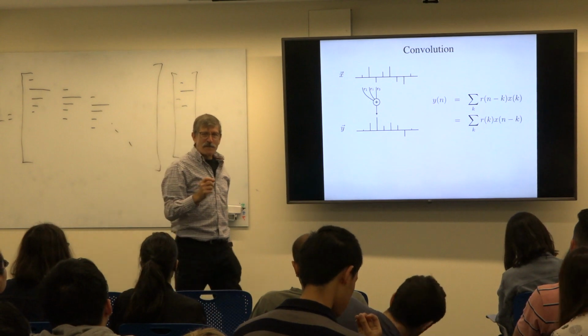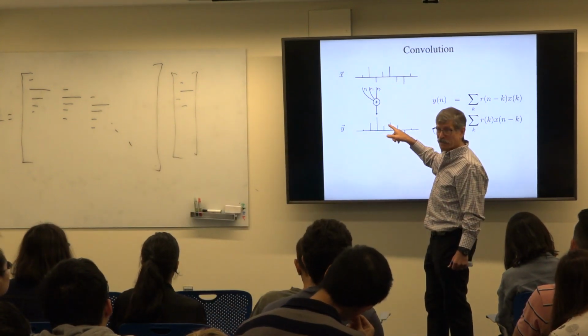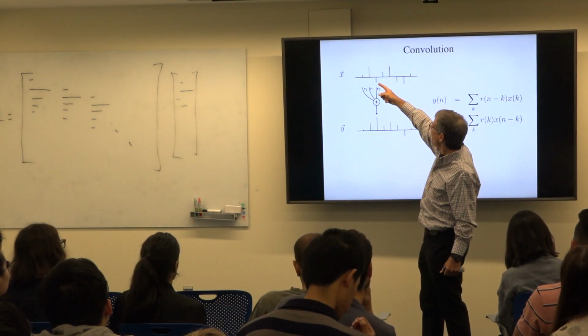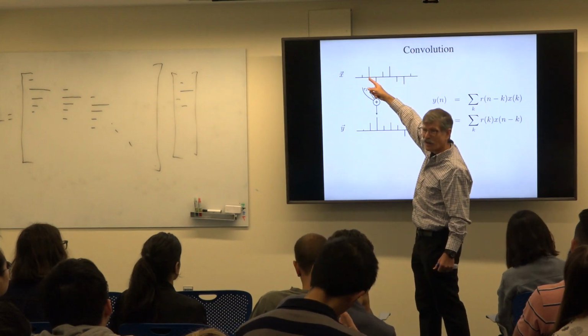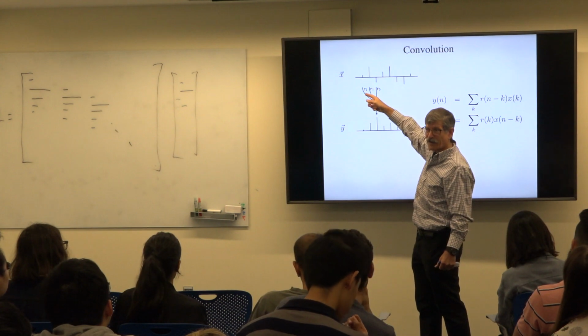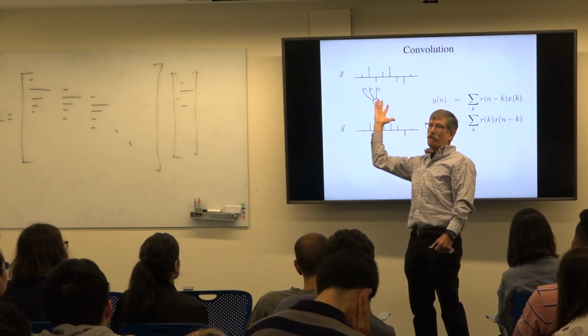So if you see what I'm spelling out here, the weights from the output perspective, what my output is now depends on the input now based on the beginning of the impulse response, the input a little while ago based on a little while ago in the impulse response, etc. In other words, these weights here are the impulse response flipped.